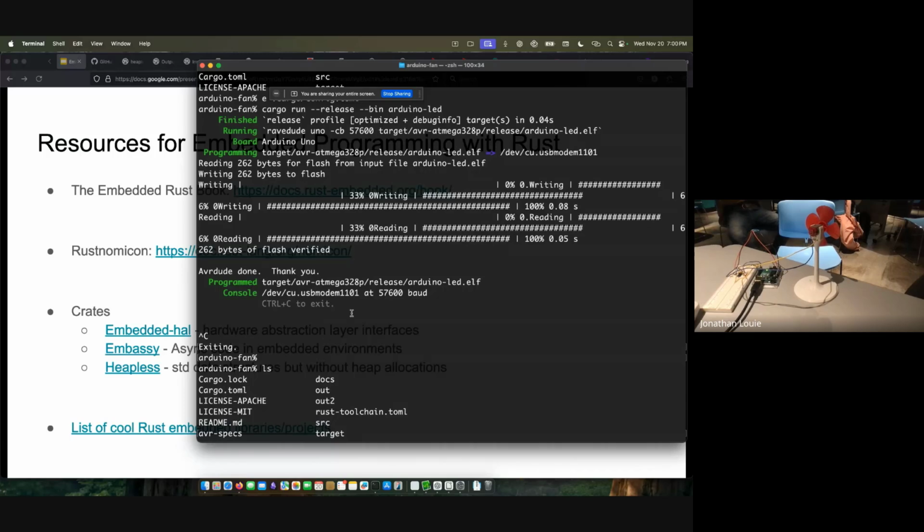Okay, yeah. So, starting with the most generic, of course, anything you can write unit tests for, write unit tests for. Designing your stuff so that it can be tested without necessarily running on the actual hardware is absolutely essential once you get beyond trivial systems like the ones that we showed here. So there are other things as well.